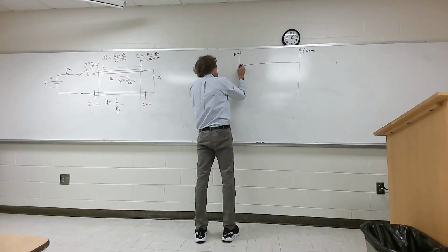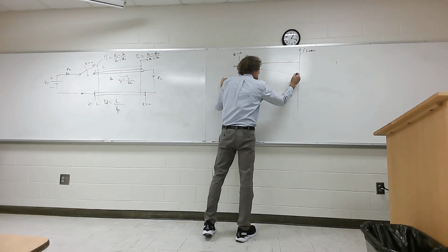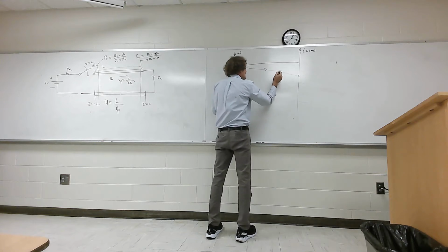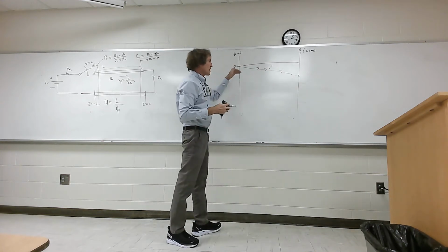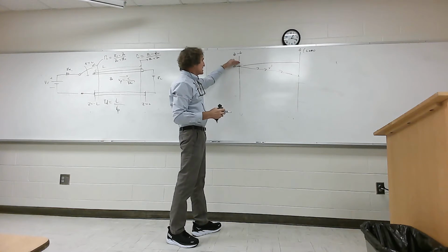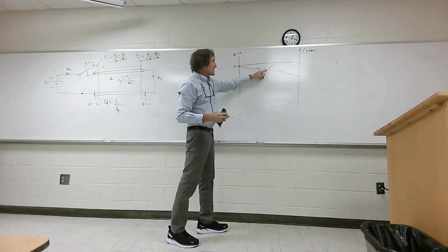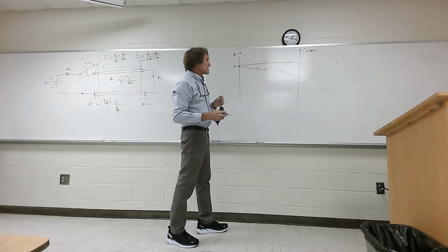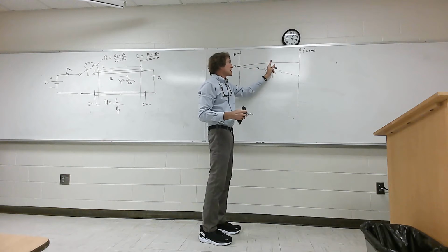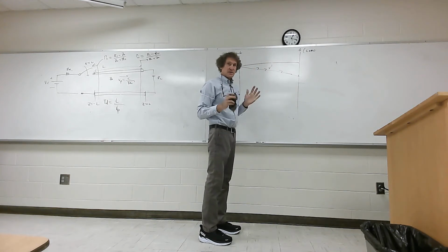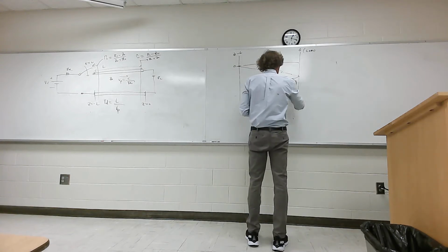We start at t equals 0 right here, and we draw a line like this, indicating where V prime is propagating. Now, if you think about this, as I go down in time this way, and I look over here, I can see an intersecting point where, at a certain time, the actual V prime waveform will move the distance down the line. It should make sense to you. Once it hits here, there's going to be a reflection coefficient.